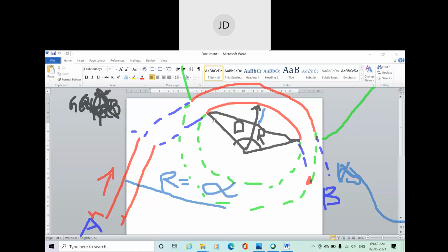And let's discuss this part roughly. We don't connect the circle directly to the straight line. We could do one thing, that we can directly connect this part like this. But we are not going to do this. We have to make a gradual increase of the value of gradient and super elevation from straight to circle. In order to connect the circular alignment or circular track with the straight curve, we introduce a new curve which is called transition curve.